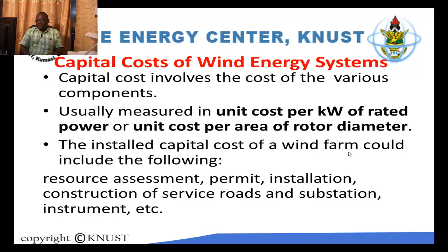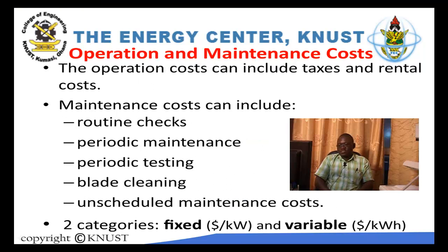And normally, wind power plants are costed in this particular way, per kilowatt. The installed capital cost, as I've explained in the beginning, includes all the costs at the initial stage: the resource assessment, permits for the land and various activities, installation, construction, engineering, road network, substation, instrumentation, and all that. All of these categories go into the capital cost of wind energy systems.